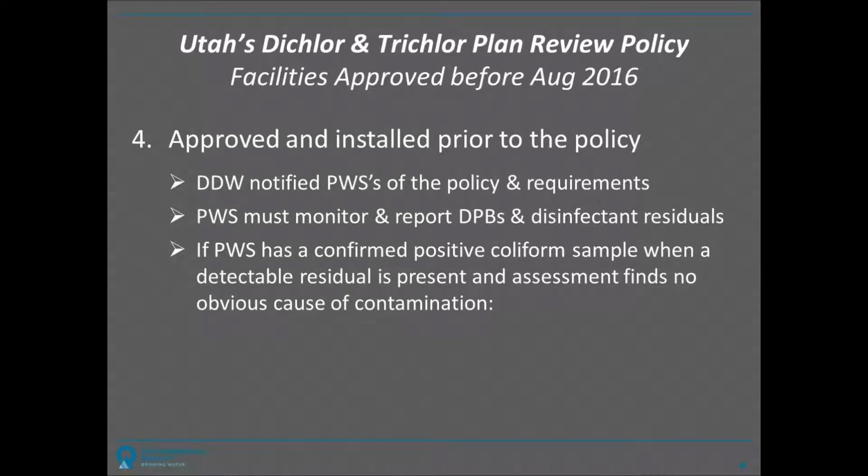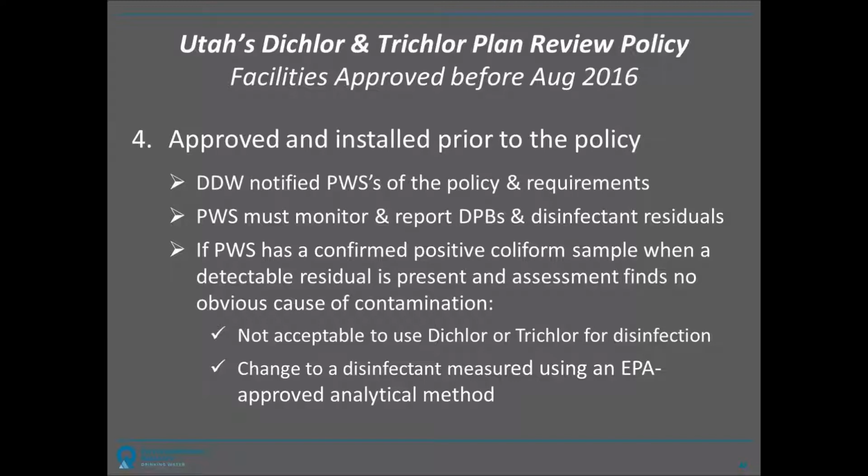However, if a water system detects a confirmed positive E. coli sample when a detectable residual is present, and our level 2 or level 1 assessment finds no obvious cause of contamination, then we're going to say for this installation, we will not accept this water system to use dichlor or trichlor for disinfection, and this water system will be required to switch to a different disinfectant that can be measured using an EPA-approved analytical method.